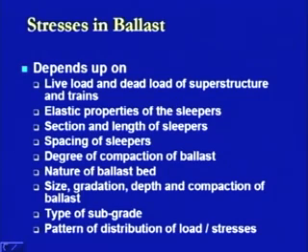Further, in continuation, the specifications related to size, gradation, depth and compaction of the ballast also have their effect. If the gradation is in such a form that all the voids have been filled and there is proper contact throughout, and a good amount of compaction is achieved because of that, and adequate thickness or depth of this cushion is provided, then obviously the stresses will get dissipated over a larger area and there will not be any failure of the ballast cushion section.